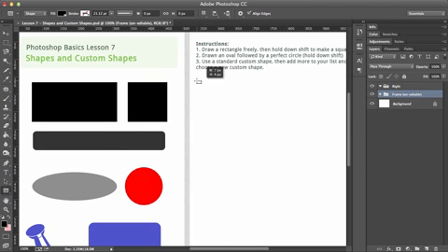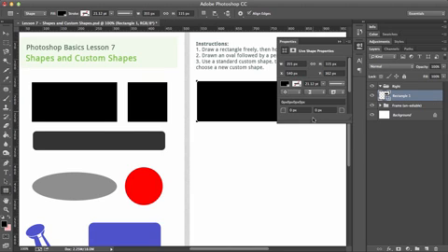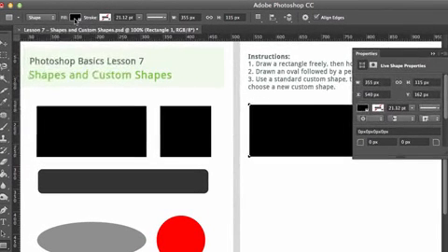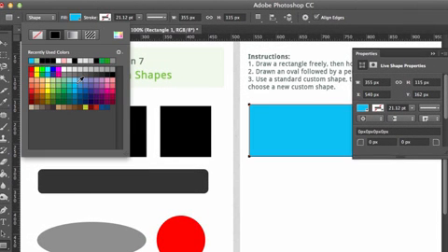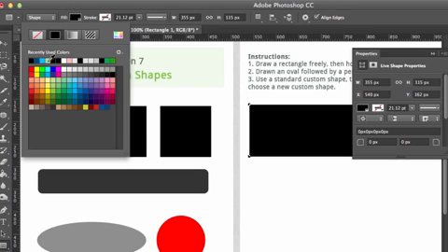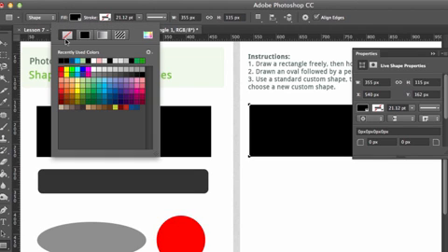Now all we need to do is drag and drop. There's one rectangle. Now we might need to change a few things. You might have like a stroke around the side of it. So let's change that now. Click on Fill, and you can change the fills here, and we're going to look at that in some detail later. And also the stroke, I'd like you to turn that off by clicking on the left one here.